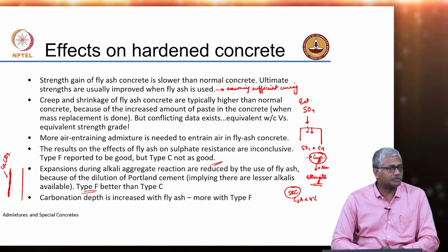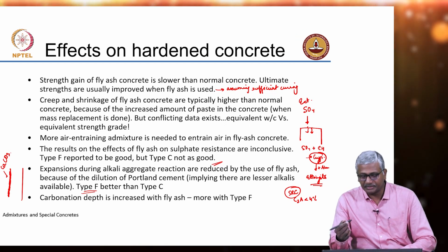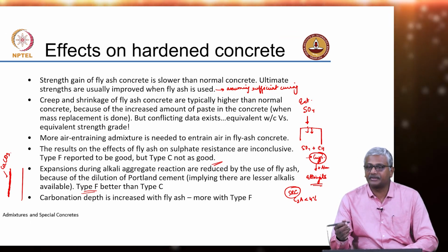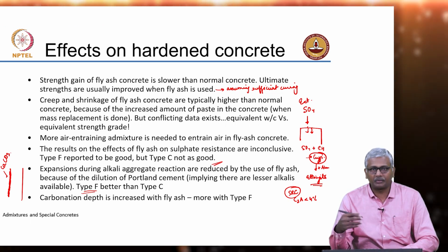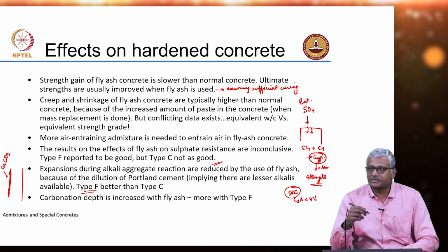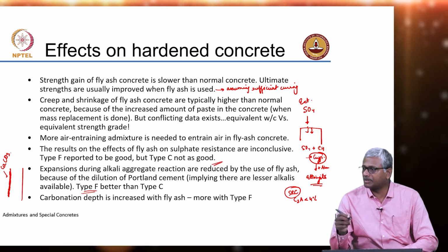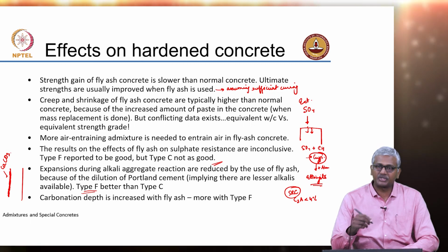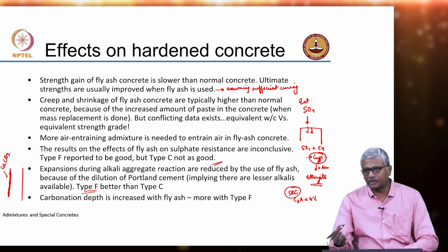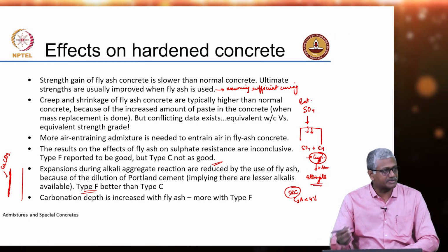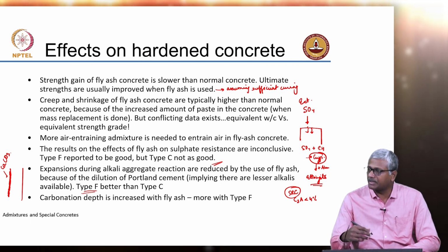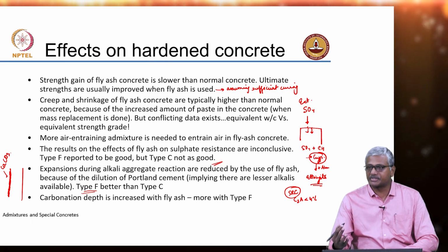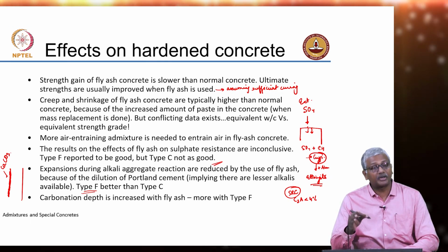Okay. So, in the past there was a report released by CPWD based on some work that was done, I think, in one of the CSIR labs, that when you substitute cement with fly ash, you are reducing pH. You will reduce some pH because calcium hydroxide consumption is happening. So, what they said is because pH is getting reduced, your concrete becomes more susceptible to corrosion. Now, because of that report,